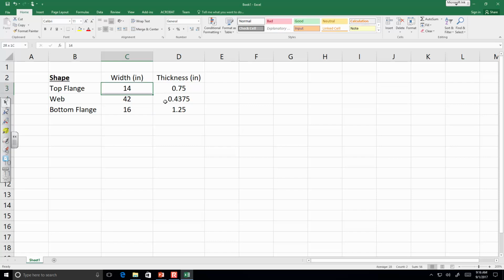Okay, now what I'm going to do is highlight these cells and box them, and here's the reason why. You can format this later however you would like, but I'm doing this because these are inputs. In other words, these values define the girder, but if I need to change the girder, then those inputs are going to change. Once I change those inputs, all of the other section properties change along with it. So I want the sheet to be robust. In other words, by changing a property, I want it to change the calculation of everything else. Everybody okay with that?